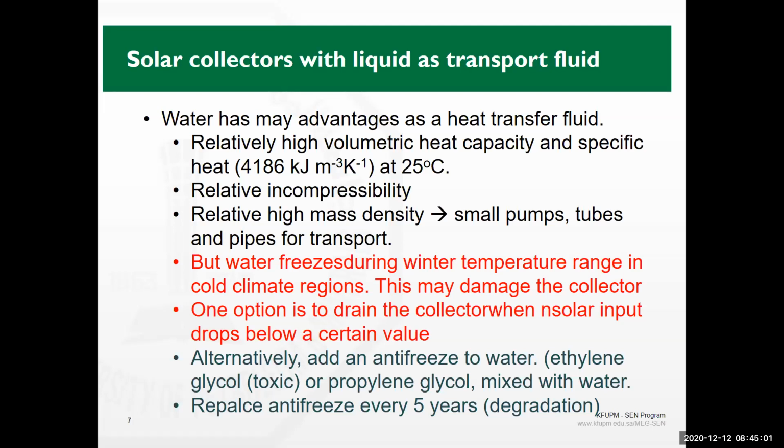The problem with water is that it freezes during winter temperature for cold climates. And water expands upon freezing, which means that it may damage the collector. So you have to do things for that. And there are 2 solutions for the issue of freezing. One of them is just to use an antifreeze, like the green water that we buy for the radiators. This is basically some sort of ethylene glycol, and the ethylene glycol has a solidifying temperature which is well below 0.